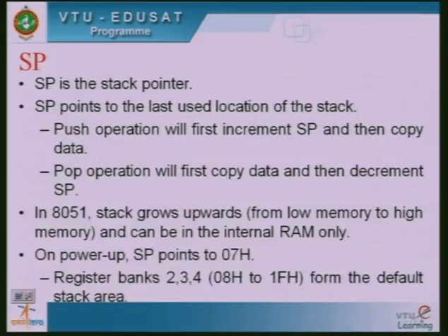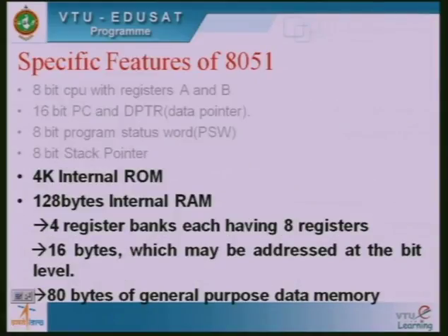On power up, as I told you before, the stack pointer will point to the lowest location, that is 07. The default register bank for the stack is register bank 1, but the higher banks, register bank 2 and 3, can also be used for the stack area. So that is about stack. Remember, stack is one specific area in memory.